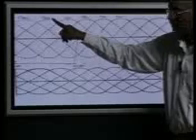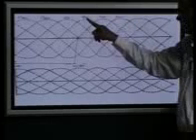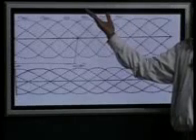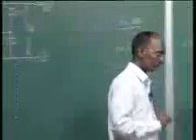How I wrote them: I first defined EBA, and then you can see this is 180 degrees. Another 120 degrees, this is 60 and 60, so that will start here. B becomes C and A becomes B, so I have written ECB. From this cycle you can see again 120 degrees here. Now C becomes A and B becomes C. For the intermediate ones, this voltage is a reversal of this, so it becomes CA rather than AC, because we have reversed the minus sign. Similarly here BC is a reverse of CB, and so on. So you have to mark the line to line voltages very clearly, top as well as bottom.